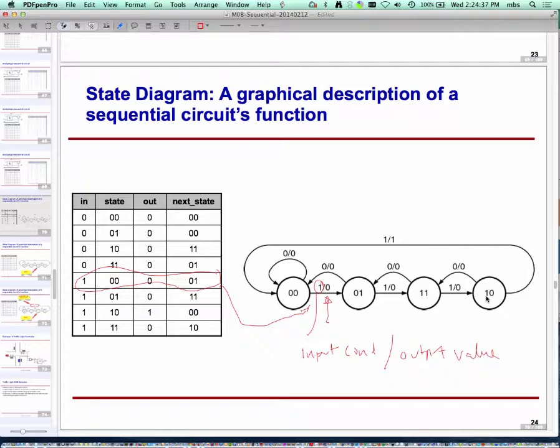So when it comes to designing state machines, a very common way is to just draw the state diagram of the finite state machine. There are specialized tools which let you do it. You can literally draw a graph like this with edges and all, and then it spits out an implementation, perhaps a description in one of the hardware design languages, or even an implementation in C or Java. So it's a very common mechanism which is used.